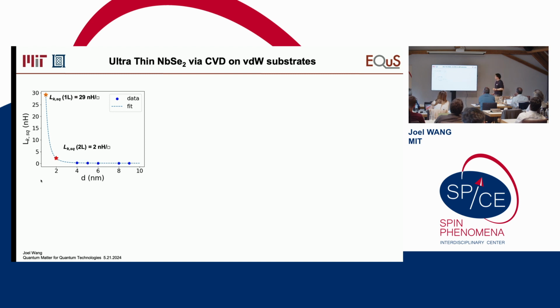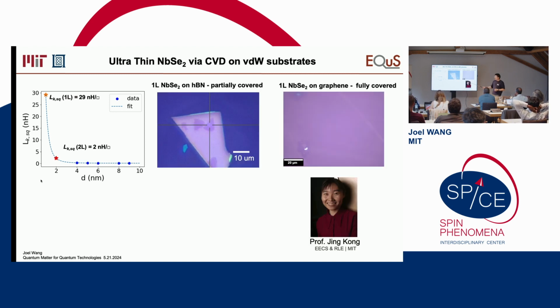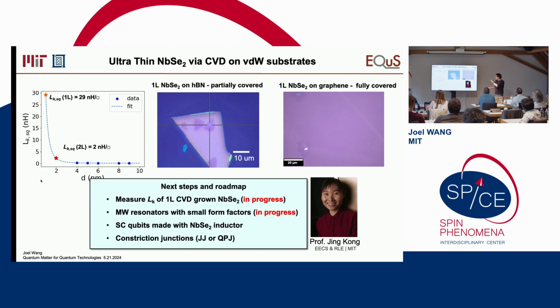layers or 1 layer. And of course, it's actually inhumane to ask a student to exfoliate and make devices like that. So for that, we actually use CVD-grown material from Professor Jing Kong's group that allows us to use the 1-layer niobium diselenide that can grow partially or even fully on different substrates. So this is something that we're working on right now. So we are measuring the kinetic inductance of the CVD-grown very thin film niobium diselenide.